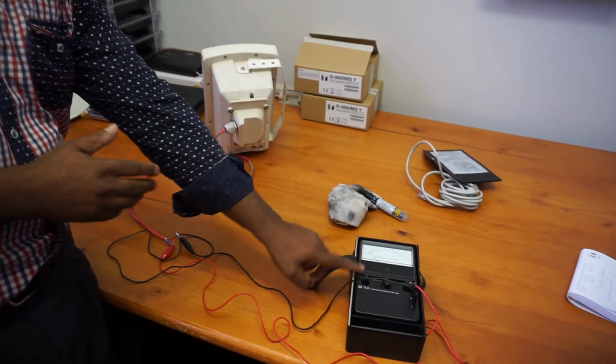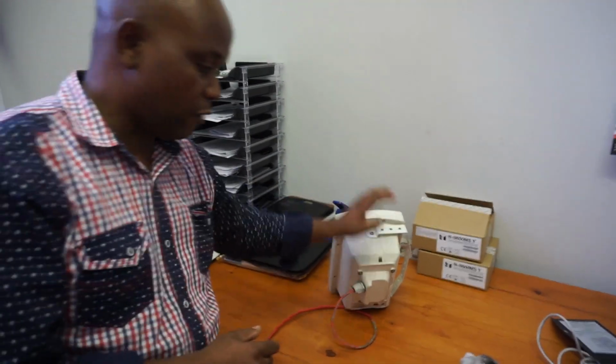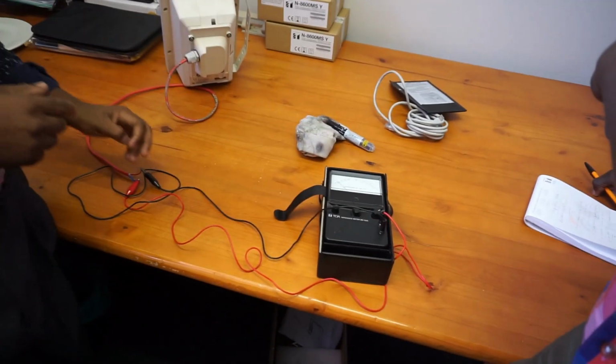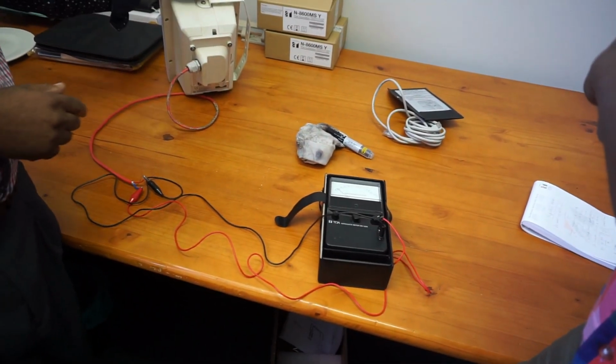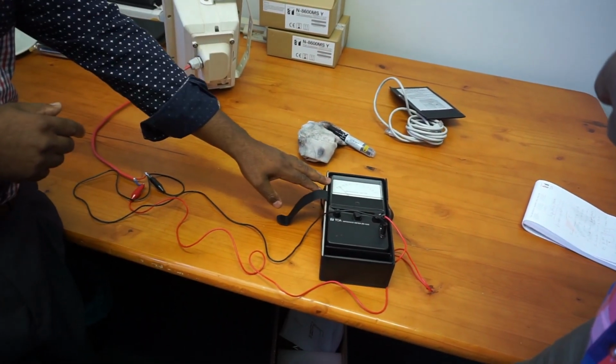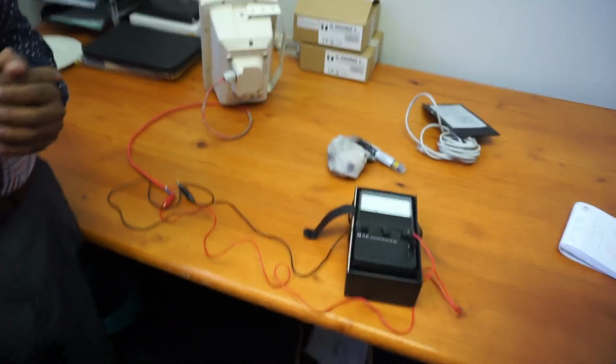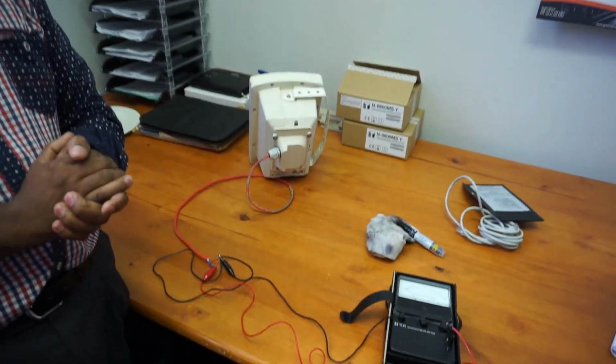So basically here I've proved the 2 kilo ohm reading, according to the impedance meter, on a scale of times 1. If I were to connect 10 of these speakers, this scale might work. But if I connect 20 of these speakers, you might find the times 1 scale is not enough. I'll then move to the times 10 scale to give me a more precise measurement.